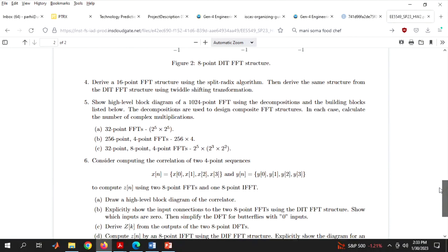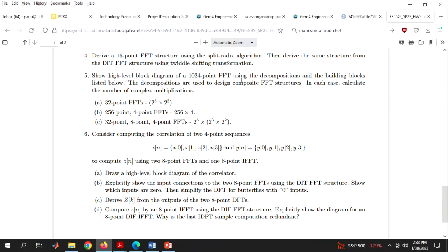Right, yes, okay. So what I am asking you here is to calculate a number of complex multiplications. Roughly speaking, if you think about the log n stages, and one of the stages has no multiplications, depending on DIT or DIF, either the first or the last has no multiplications, and the other one has n by 2.